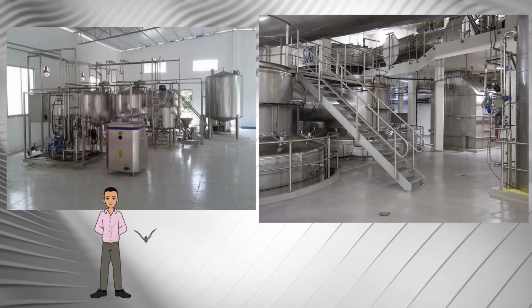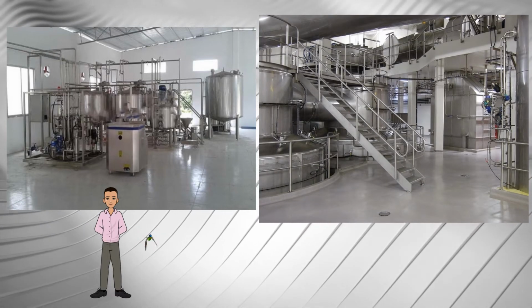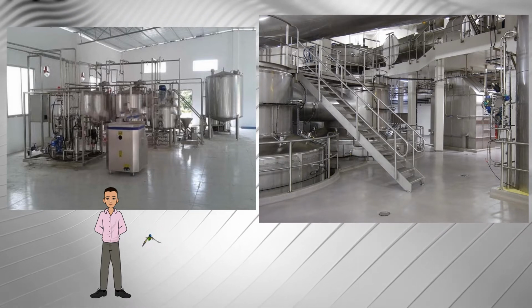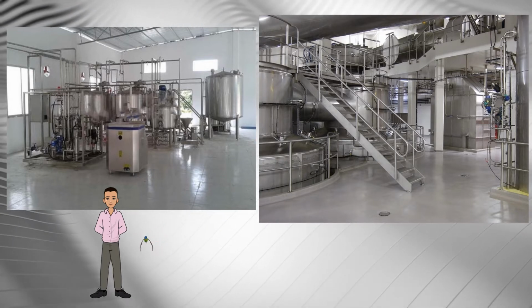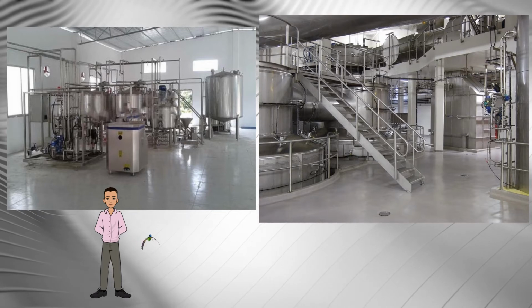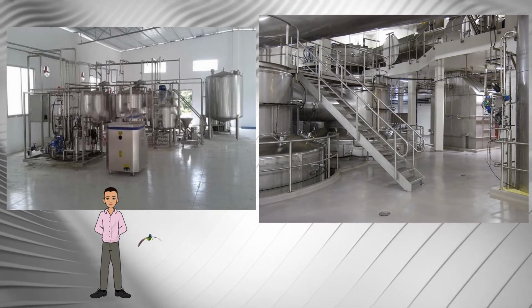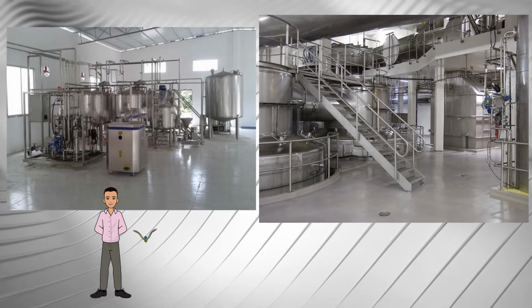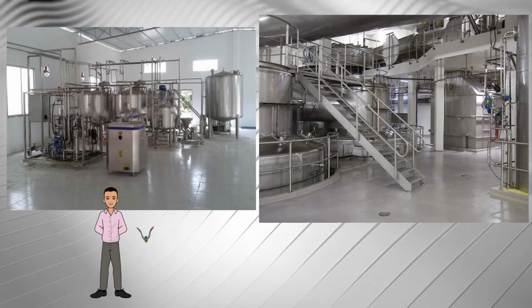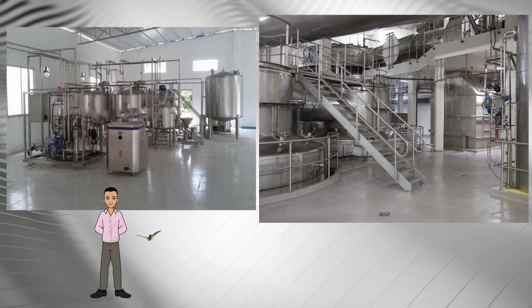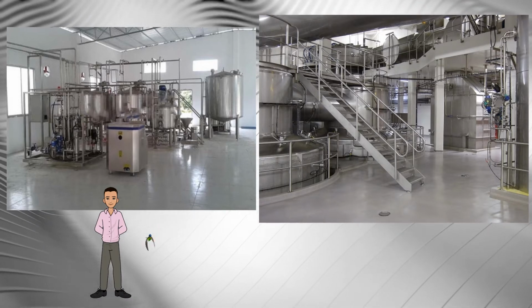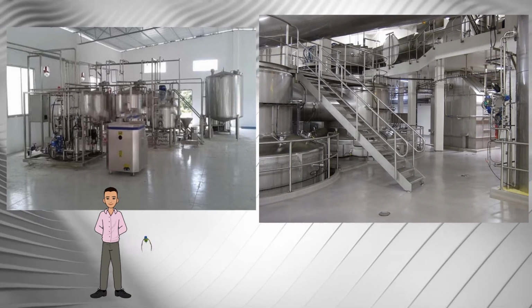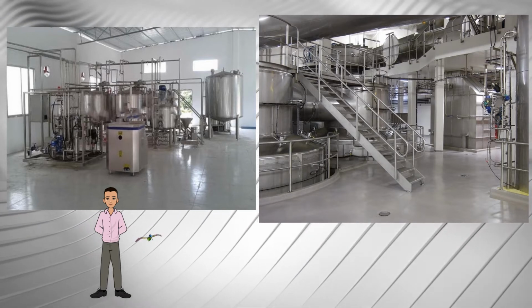The large amount of air injected in the process requires outlet cyclone to extract milk powder from the exhaust air. Even with regular maintenance, cyclones are never 100% efficient, so that some powder, which can accumulate quickly, escapes. Deposits of powder can cause problems with roof drainage, which therefore require appropriate design.